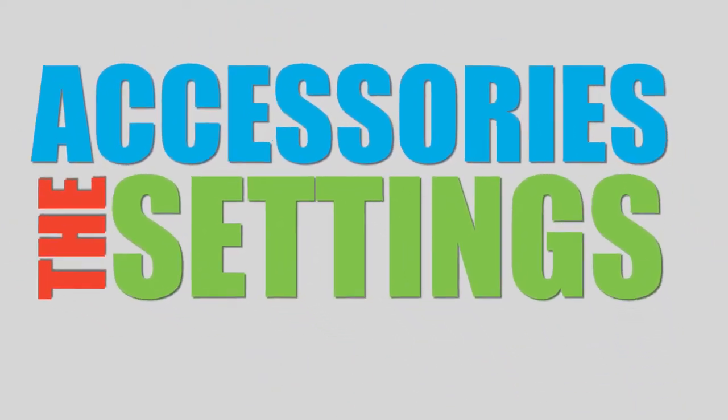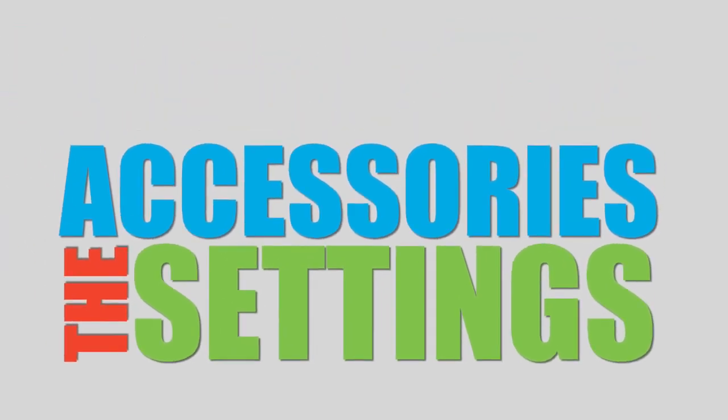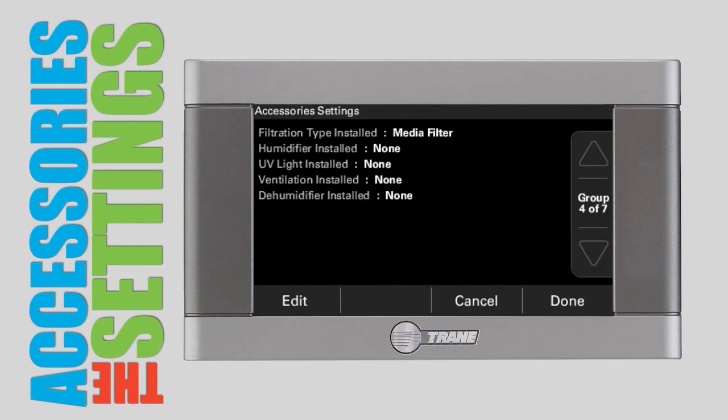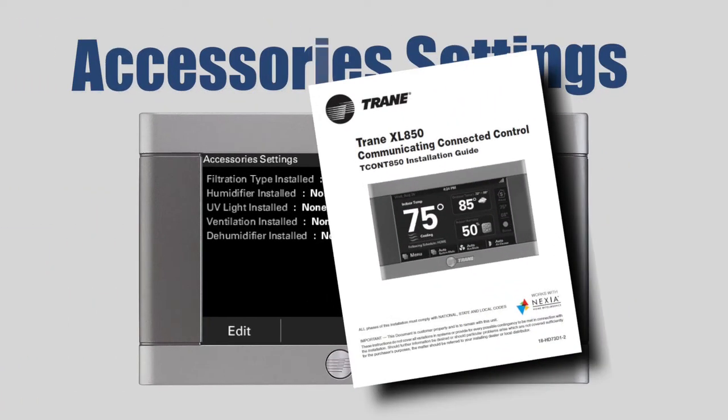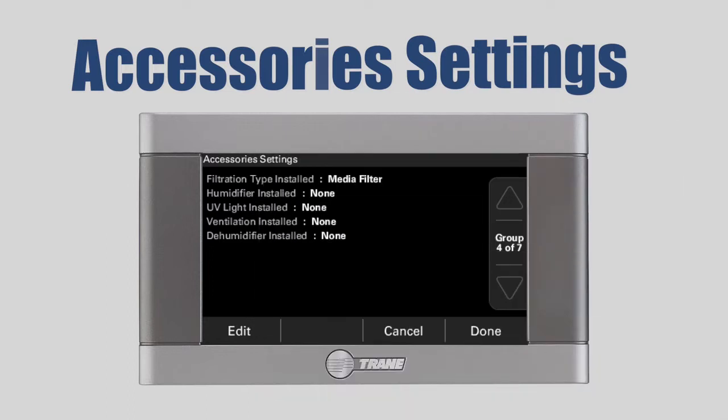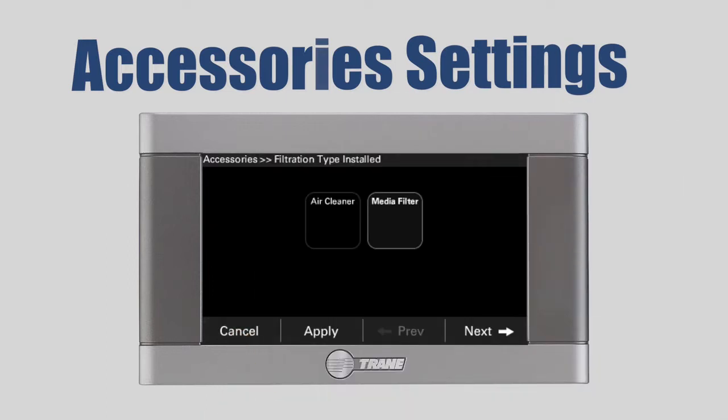Accessories Settings. Accessories setting allows the setup of installed accessories. For detailed information on all accessory options, see the Advanced Operations section of the Installer's Guide. From the Accessories Settings summary screen, press Edit. Select the filtration type and press Next.